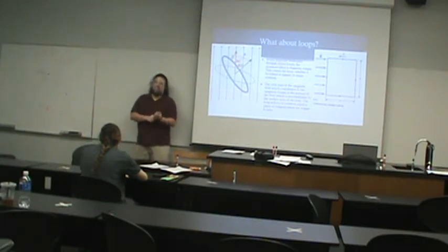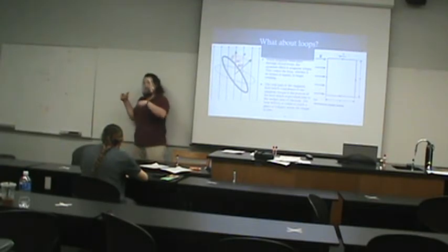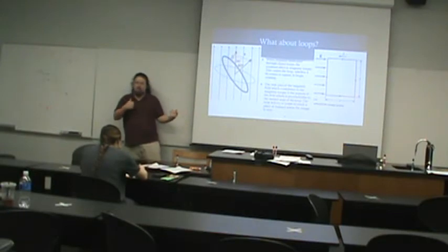Because if instead of running current through the wire and letting the magnet turn the loop, you could instead crank the loop by hand, like maybe put a handle on it or a water wheel and just crank, and that, because you're now spinning it through a magnetic field, would create electric current in the wire. So a motor and a generator are the same machine, just run backwards.